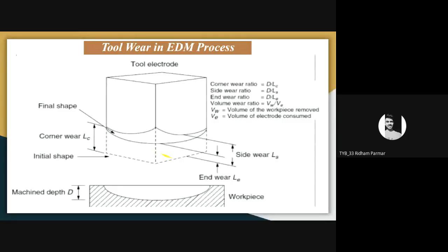And if you want to go for the calculation of volume wear rate, then you can take just the ratio of volume of the workpiece removed divided by volume of electrode consumed. So that simple formula you can use.